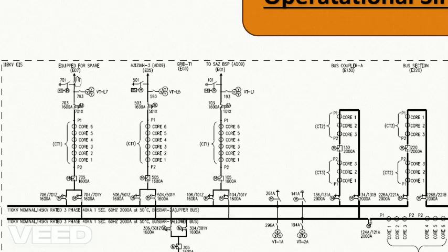Transients, switching transients, can carry huge energy and damage the expensive equipment. So suitable surge arresters are used here to suppress that energy, blocking the energy which is not desired to flow in this direction.